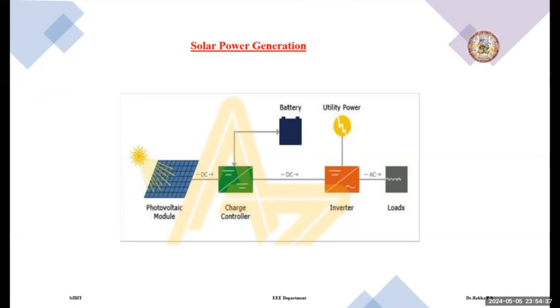On forming the PN junction, the electrons of the N-type material try to reach the P region, creating a negatively charged layer. Similarly, the holes of the P-type material try to reach the N region, creating a positively charged layer. This region between the 2 layers is known as the depletion region.